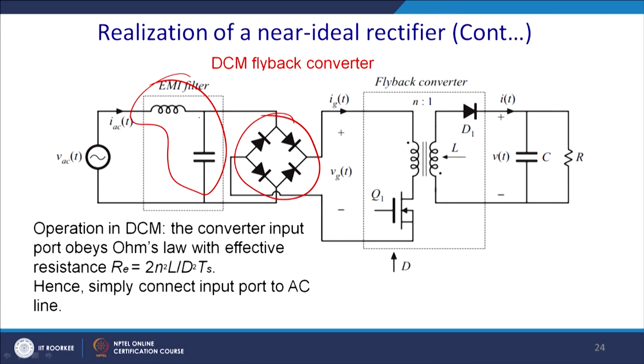This is the rectification, and ultimately we get the DC. Please mind that there is no capacitor, so we get a double frequency ripple in the output. And this is the MOSFET in most cases, because the power rating of these devices is quite low.